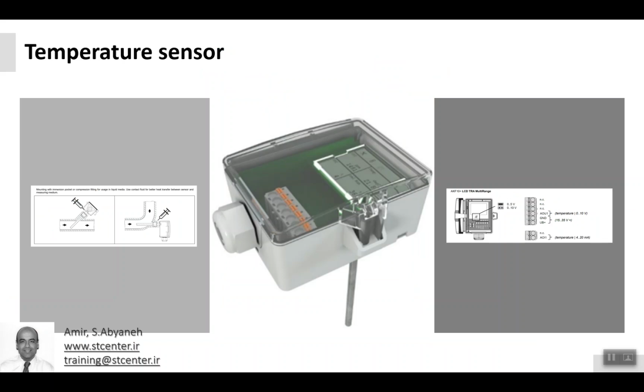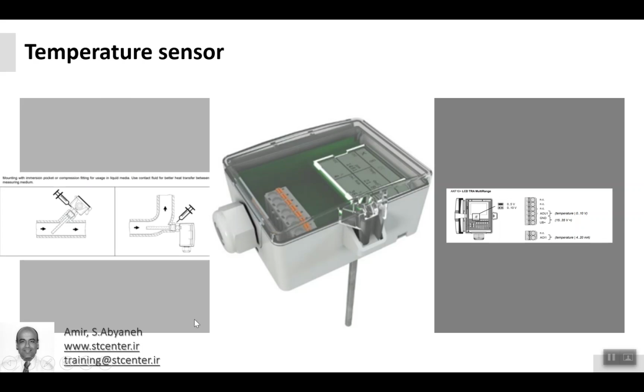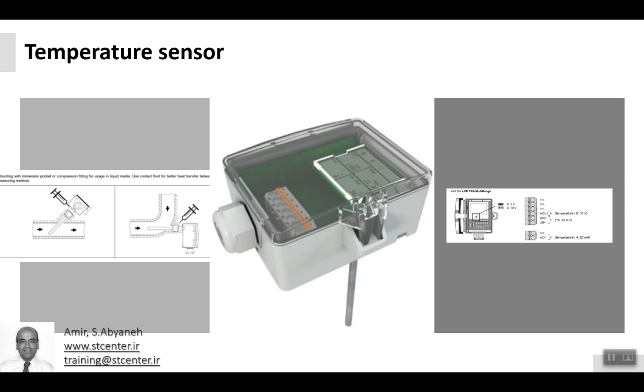That's great. So you get some insight into the air handling unit. Now I want to talk more about the different sensors. We already covered temperature sensors. You remember we use the immersion temperature sensor for the cold coil and hot coil. The important thing is how you place it. Always you should go to the datasheet. You can see the direction of the installation.